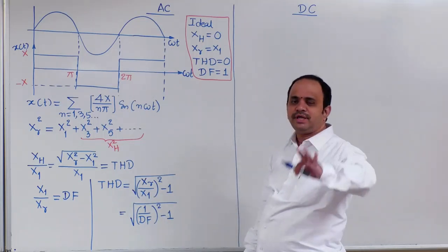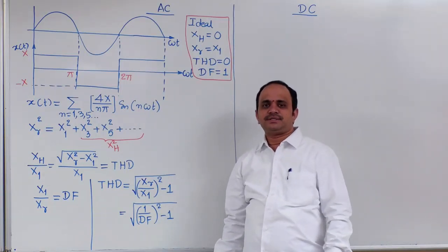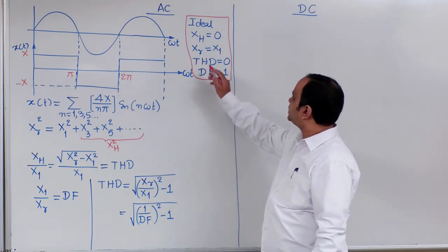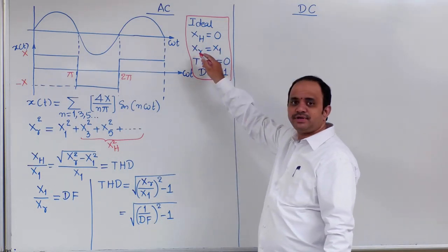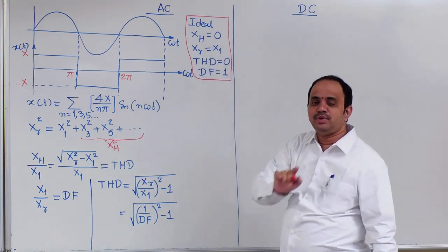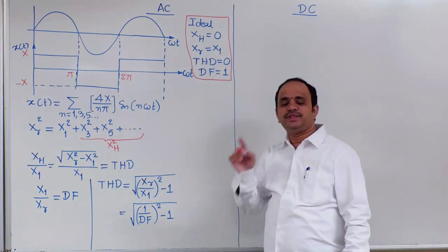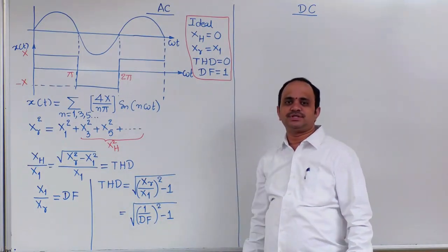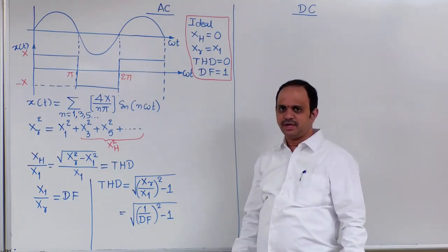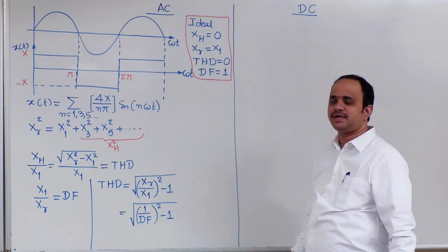So going forward in the analysis, if you come across AC waveform but it is not a sinusoidal function, then you have to calculate RMS value of the overall function and RMS value of the fundamental component. From where you will get RMS value of the fundamental? From Fourier series analysis. With that reason, in our beginning lectures, we did Fourier analysis for some standard repeated waveforms. Okay, we will use all of those conclusions for this particular topic to understand.